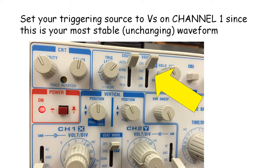And here I've done the trigger. Remember all that triggering problem we had in multisim? Well, I made the source of my trigger channel 1, and this is where you adjust the level of the trigger. So if you want it to look like a cosine, you can move this knob back and forth until you're triggering at just the voltage you want. I've got the coupling automatic, and you might have to fiddle with this, either normal or automatic. I don't know what the difference is, but sometimes it works on one and not the other, and sometimes it's the other way around.